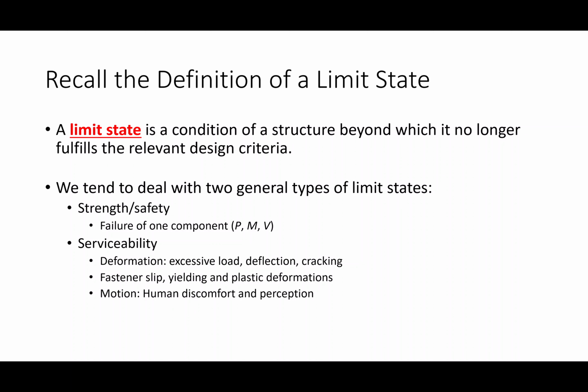Now, that is an example of low cycle fatigue. You put it through a very small number of cycles, and then it fractures. Well, bridges are subjected to high cycle fatigue. I mean, think about it like this. If you have a bridge that's carrying traffic on, let's say, 3rd Avenue, how many vehicles go across 3rd Avenue in a given day? Take that and multiply it by 365 days a year. AASHTO says that we design bridges for a 75-year design life. Do the math. That's a lot of cycles, right?